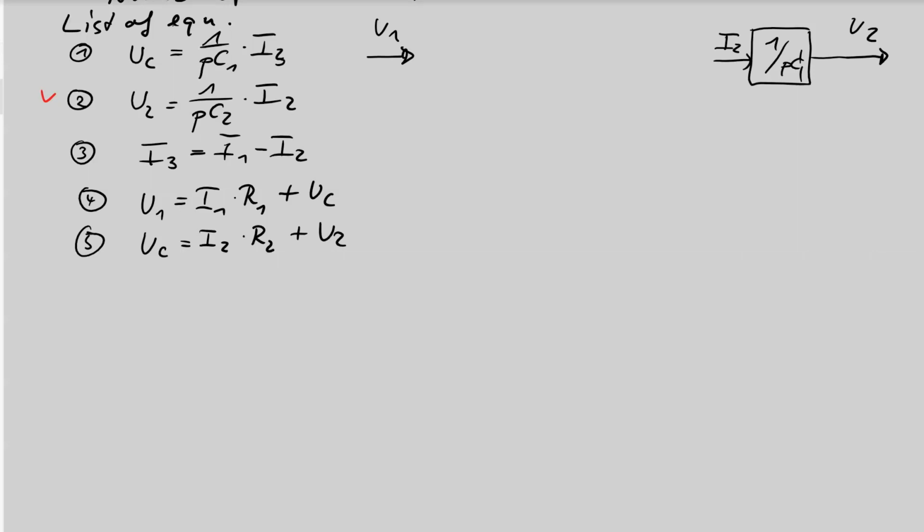I should never use the second equation again, but I want to show you what happens if you, in spite of my information, do this. You forget, you go now drink a coffee, come 10 minutes later back, you have forgotten which equation you have used. You have an open input I2. Now you look for an equation which contains I2. You see this equation is possible, this equation is possible, but this equation is also possible. What happens if you now use equation 2,